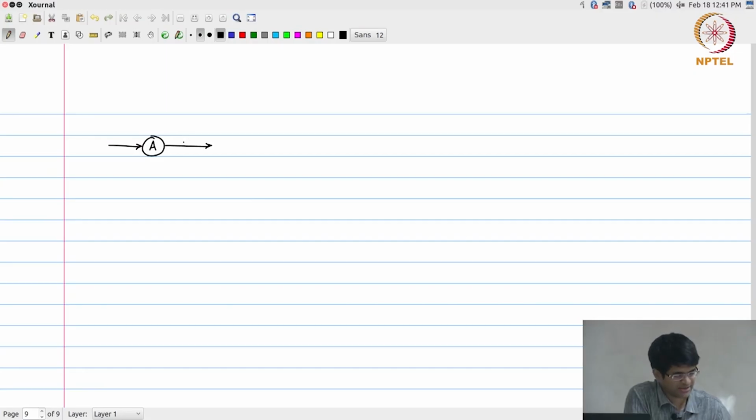What I mean by retiming, in other words, is, let us say that I had a functional node which looks like this and it has a delay on its output. These two I claim are essentially the same thing, which is pretty much what I started off with at the beginning of this lecture by saying that systems are time invariant. The fact that I have shifted a register from the output side to the input side does not change the functionality that is finally going to be observed.